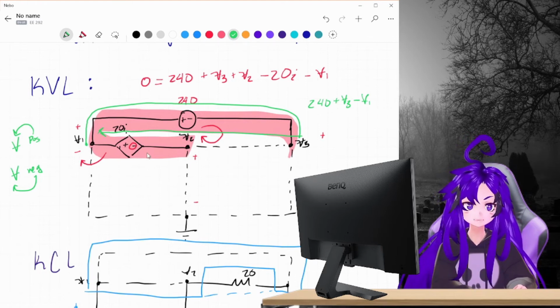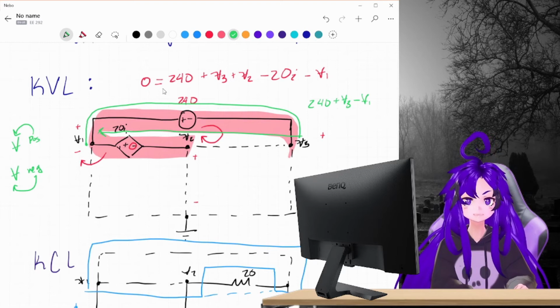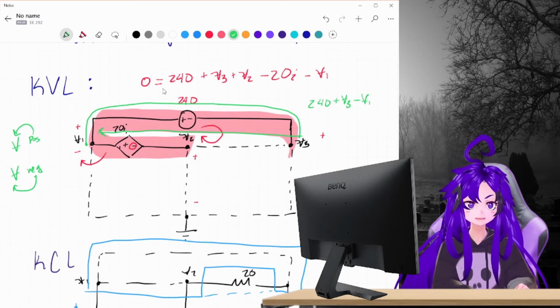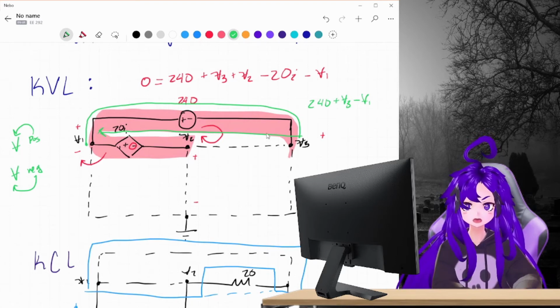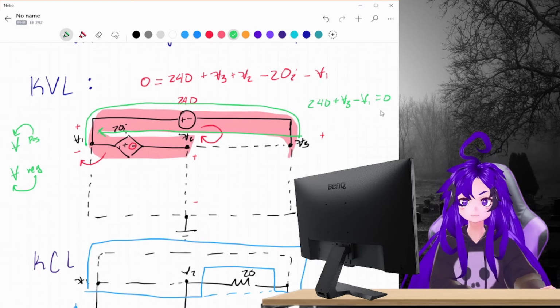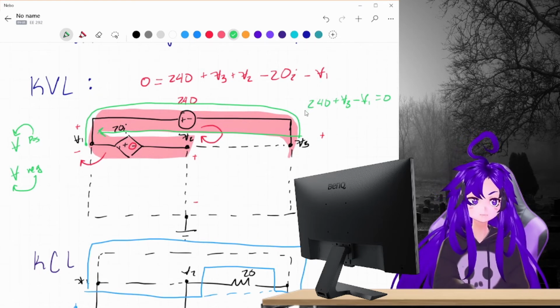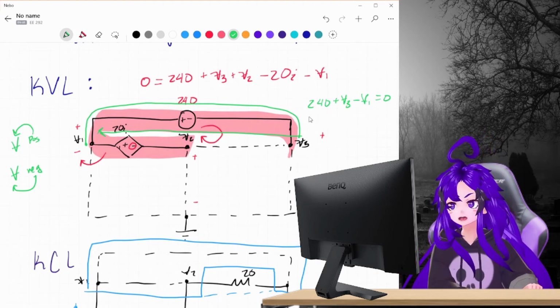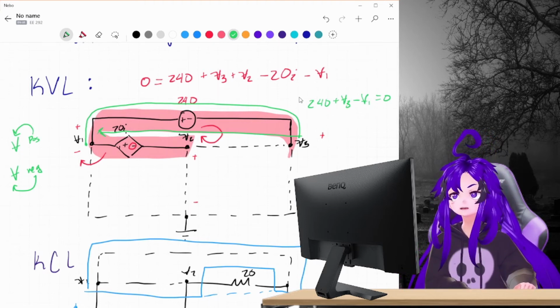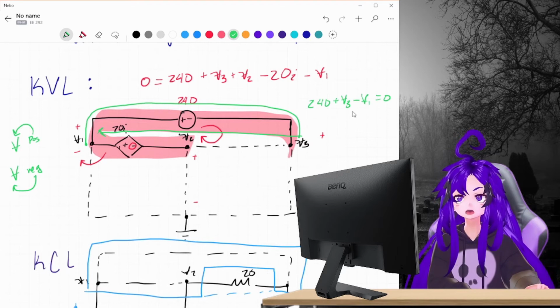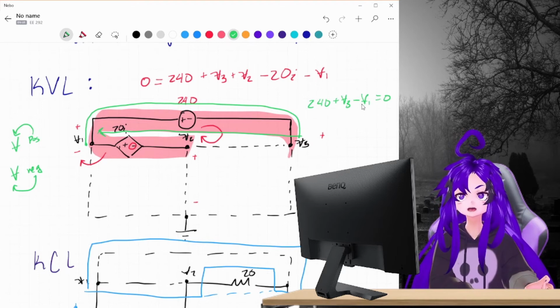If you decided that all voltage sources were upside down, you just better make sure that you keep it consistent. Everything about engineering practice is keep your conventions consistent. If you have to write them down at the top of your page, do it. I have done it for years. So it's fine. Use whatever you need to, do whatever you need to make this easy on you. Okay, so anyway, this is our first one. So this is how we're gonna relate V1 and V3.